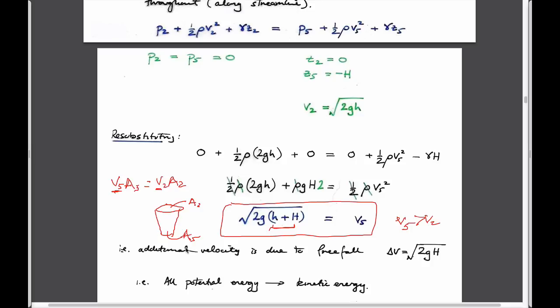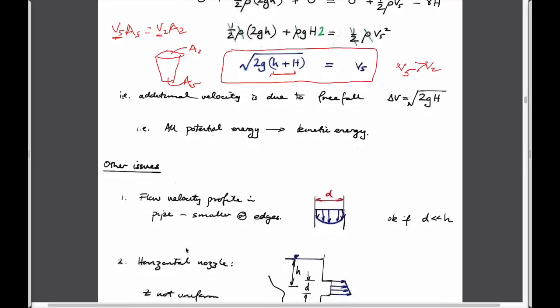And if you look very carefully at a tap, a faucet that's running, you see it comes out of the faucet at some width, and as it goes down in free fall, it gets slightly narrower. And it gets narrower according to this basic relationship. And so a couple of the reasons that we didn't do the jet lev with this big column of water is that if you make the column of water small, you avoid two problems. You don't have to factor in the weight of that water when you're doing your free body to calculate the pressure that's acting up on the bottom. And you also don't have to account for the fact that the areas change as you go down through the jet, as you go down through the system.